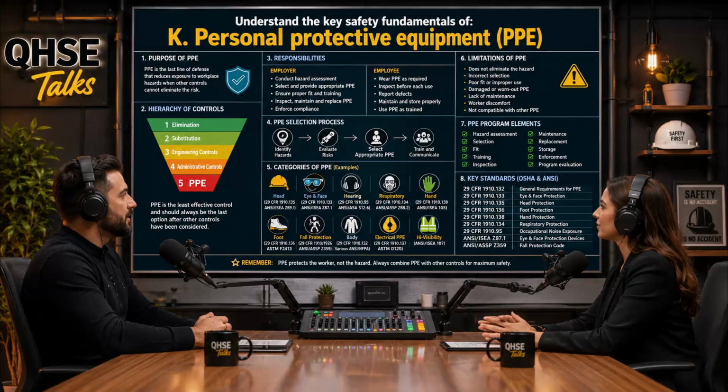Like a pressurized scuba tank in SCBA. Exactly. Or through a long, high-pressure airline tethered to a compressor outside the hazard zone. And air purifying respirators. Those force the worker to breathe the ambient contaminated air, but they pull that air through a highly specific filter or chemical cartridge to scrub out the hazard before it reaches the lungs. And we're scrubbing out 6 distinct types of airborne hazards.